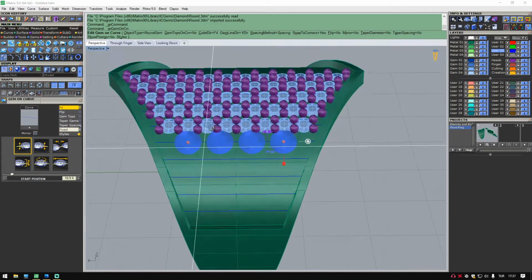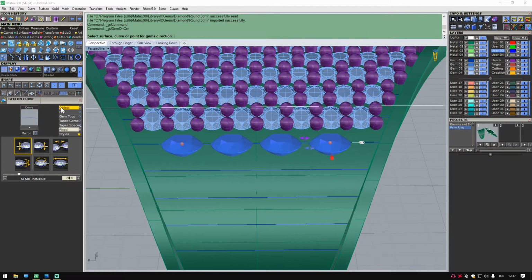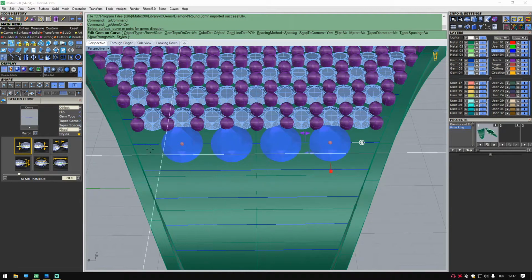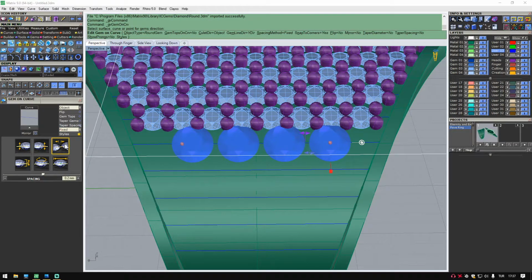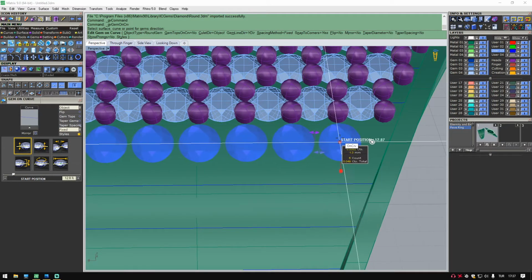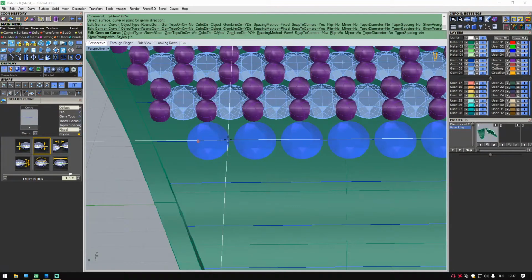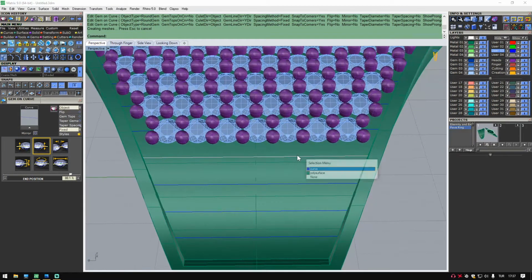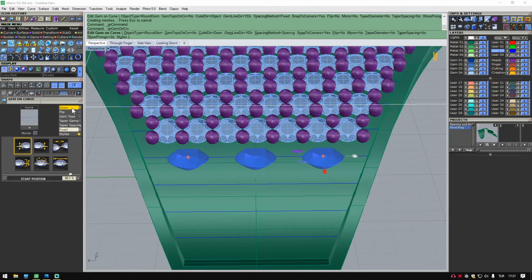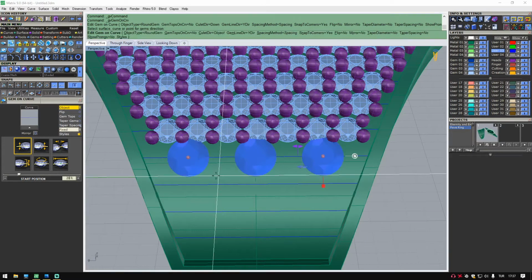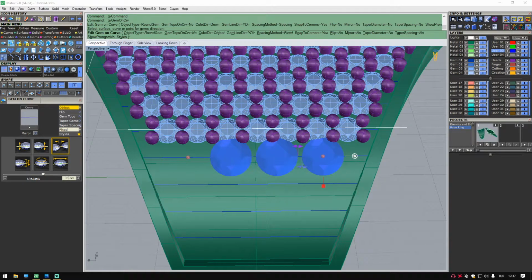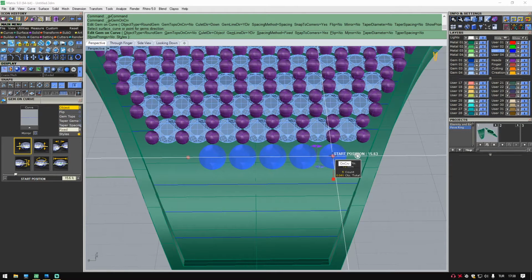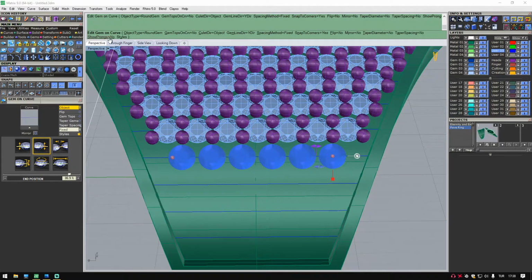You get the idea. The command starts working. Change this into object, click on your surface, fixed, spacing, size gems, fixed again. The spacing in between 0.13, the gemstone size 1.3, the start goes there, the end goes there, and show prongs, yes. One more time, F4, object, spacing fixed, in between 0.13, gemstones 1.3, show prongs, yes.